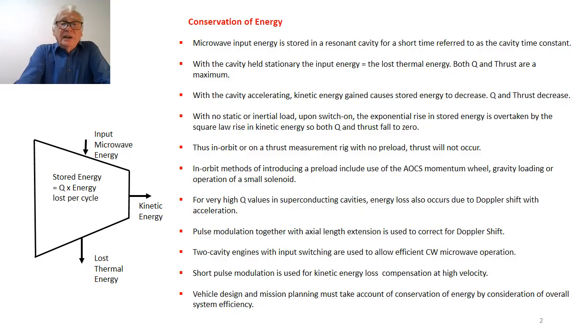And in this case, if the cavity is completely free to accelerate, both Q and the thrust will fall to 0, which is pretty unsatisfactory if you're switching on the thruster in orbit, or indeed switching it on in a thrust measurement rig that has no load on the cavity itself, no mechanical preload is applied.